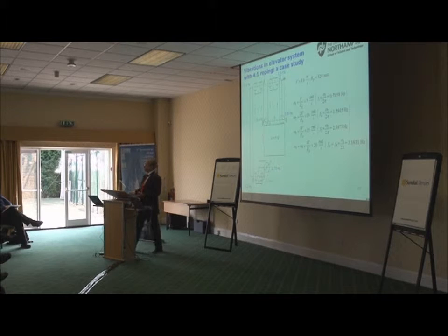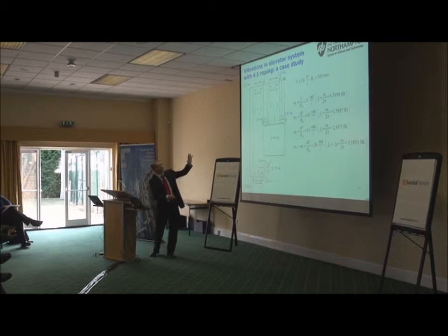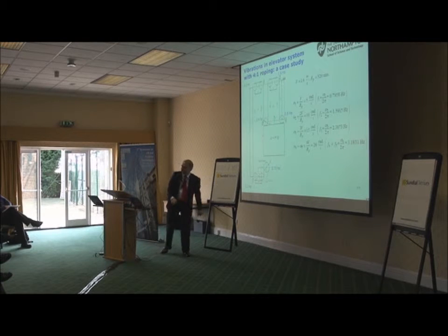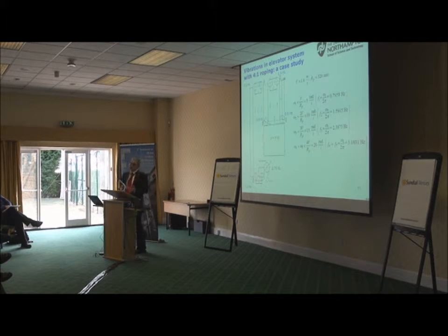The calculation is very simple. We do kinematic analysis. Essentially the frequency omega is equal to velocity divided by radius. In this case, the pulleys rotate with 1, 2, 3, 4, 5 frequencies, with values ranging from quite low, where the first pulley is about 0.8 Hertz. The next will be this multiplied by 2, 1.6, multiplied by 3, 2.4, times 4, 3.2. Okay, so we've got the frequencies in the system.